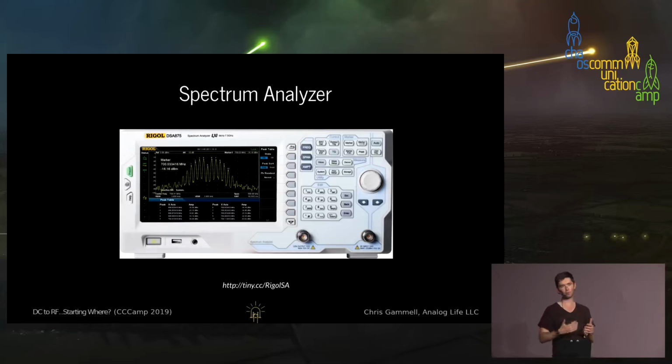But really anything that's outputting its own signal, right? A phone is going to generate its own signal. Again, a Wi-Fi chip is going to generate its own signal. You then could take that signal and look at what it's actually outputting in the spectrum on a spectrum analyzer. What we were looking at earlier was a slightly different thing. That was an oscilloscope. That's showing the time domain, and then it has an FFT, which is a measure of the frequency, and it's basically a very tiny software version of what we're looking at here.